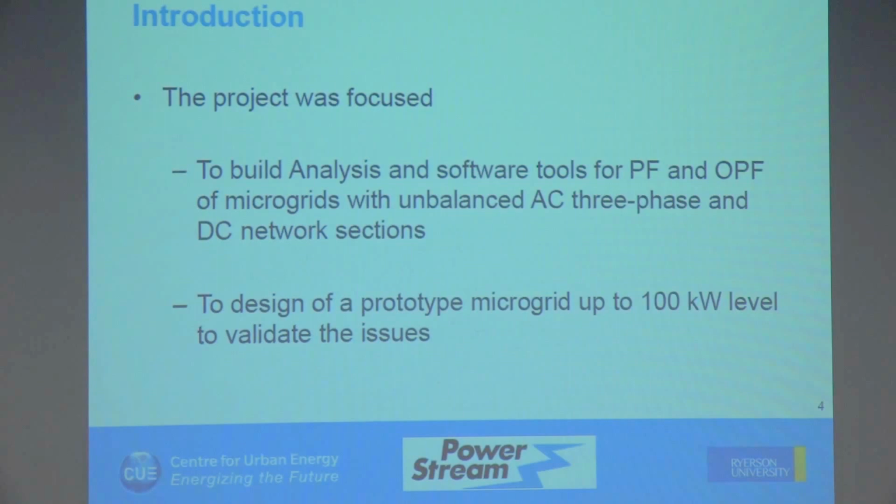So if I take a common analysis tool such as PSS/E or PSS SynCal, you cannot actually model what we have modeled here as a microgrid that I explained to you and analyze it in those tools. Which is why we say it's not possible to use a commercial tool at this time to analyze a microgrid in its entirety.